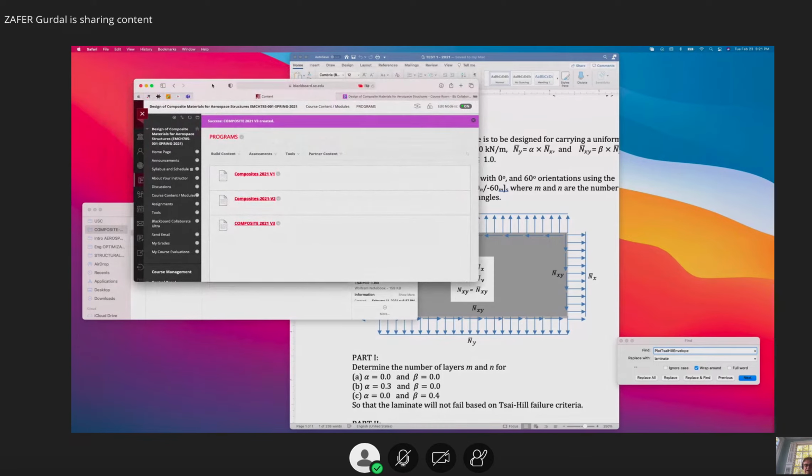And if I have the time, I will also check and make a comparison to find a more conservative approach, whether in the Sigma 1, Sigma 2 product, it'll be more conservative to use XT square or XC square or XT XC combination.